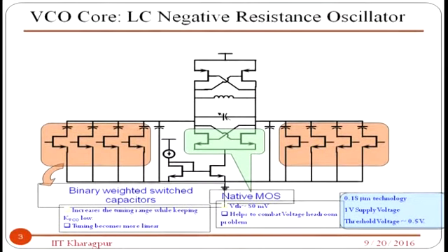And then within this 2.401 and 2.4, I can tune it with fine tuning using the varactors. Clear? So I have two tuning characteristics: one by band select switch capacitors, and the other by fine tuning with the variable capacitors. So if now delta V is 0.2 and your frequency tuning range is 5 megahertz, then 5 megahertz divided by 0.2 becomes 25 megahertz per volt.